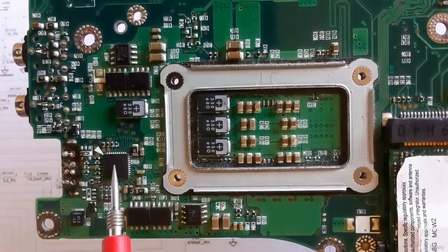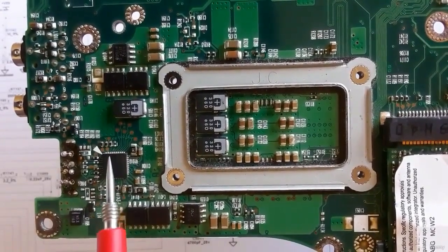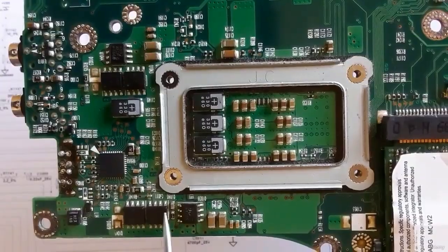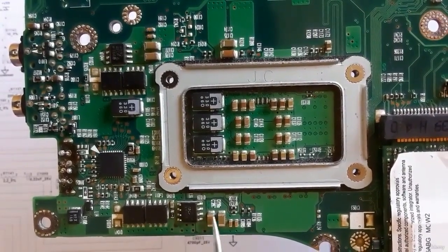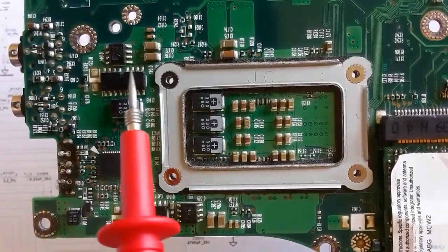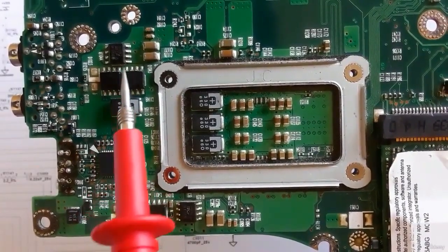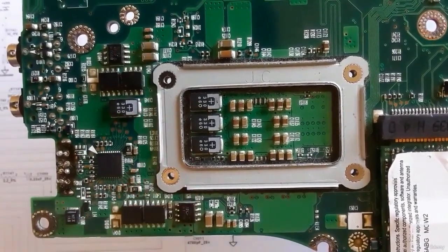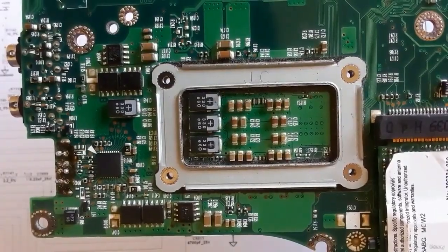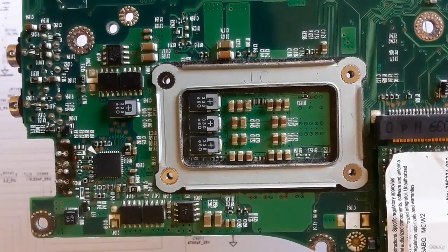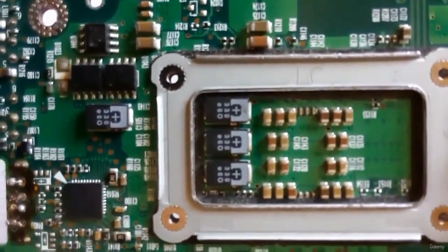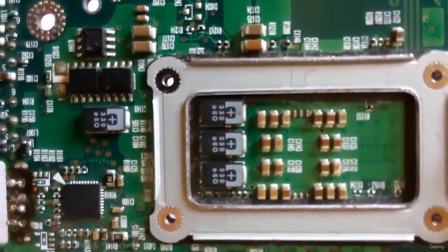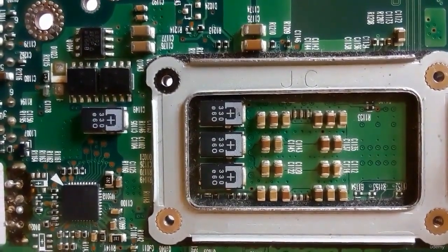So this is the CPU power management IC here, okay? And these are the MOSFETs, three MOSFETs for the first channel, and four ceramic capacitors, and the other three MOSFETs for the second channel with four ceramic capacitors, okay? So this is the back of the CPU circuit. Here, many ceramic capacitors and chemical capacitors or polarized capacitors.